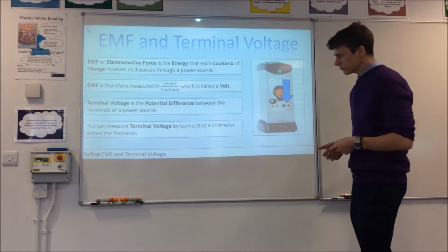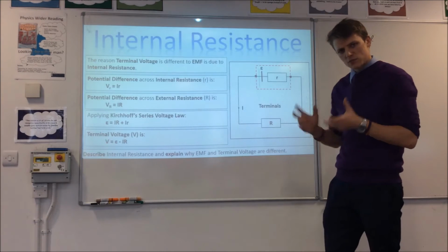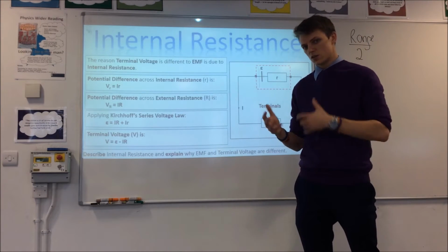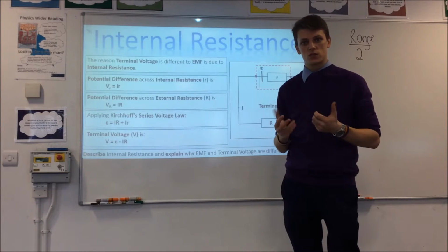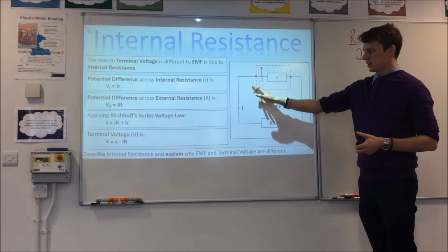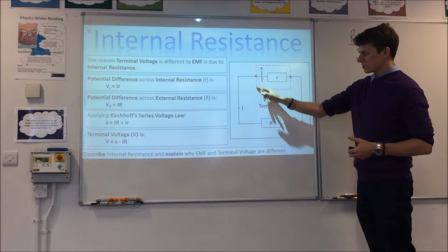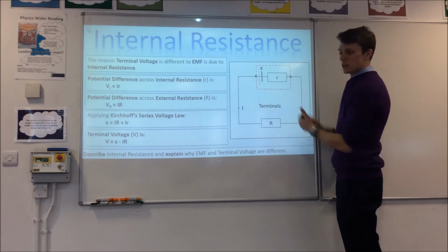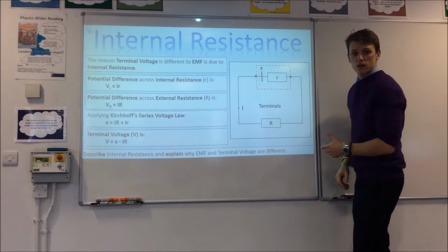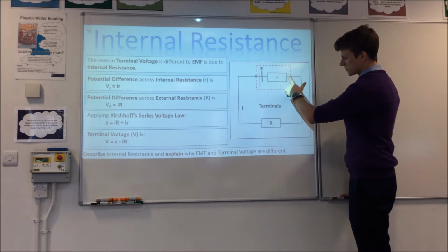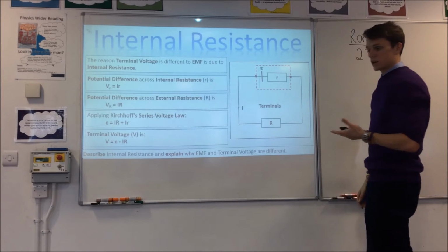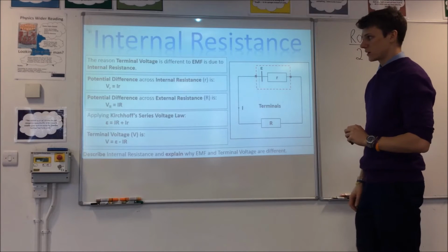Like I was saying, the reason it's lost some energy is because there's something called internal resistance. There are sources of energy loss inside your battery that we model as a resistor. You'll very often see it like this, and I put them in a dotted box to say this is actually your whole battery, and these are the terminals of your battery. So you can see it would have already lost some potential difference before it even reaches your circuit, or the terminals to go to your circuit.